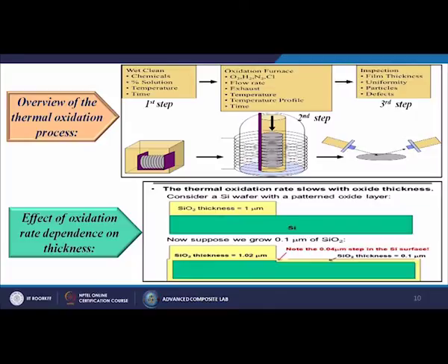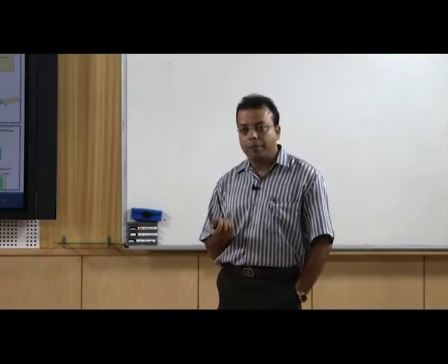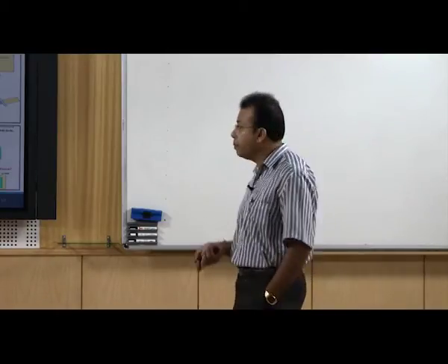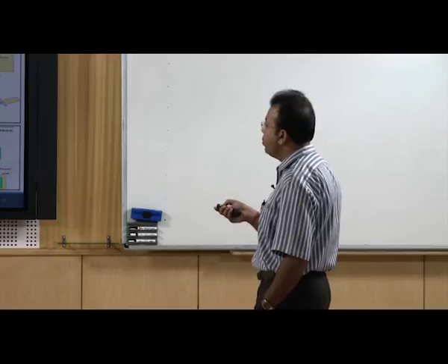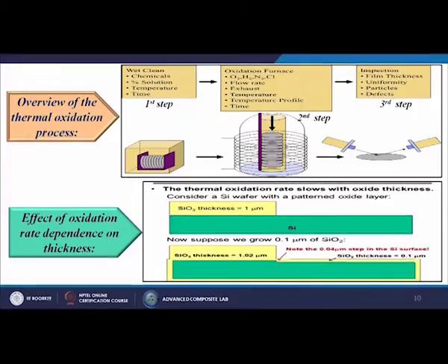then we have the options to increase or decrease the temperature, because sometimes, depending upon the temperature, various chemical reactions take place, and then we have to keep the time over there. Then the last one is called the inspection, where we can check the film thickness, uniformity, particles, and whether there are any defects on the substrate or not, whether the coating is homogeneous or heterogeneous, or whether the layer thickness is continuous throughout the surface or not.